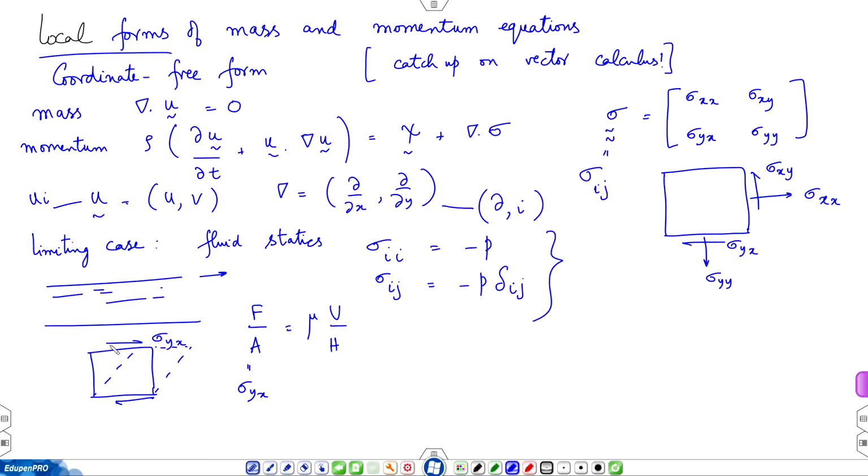So, if you think of this at the elemental level, a small interval of time delta t, then let us say a point such as A will move to a point such as A prime. How much is that movement? It is some velocity times delta t, that is the distance. And how much is the shear deformation? That is the angle through which that edge has moved. We are talking about small increments in time. So, the angle is also small.